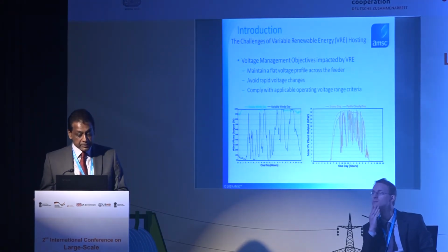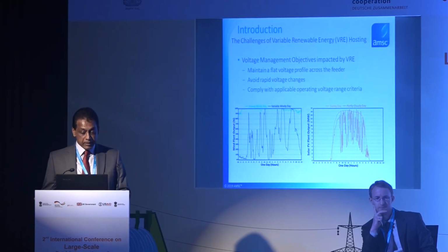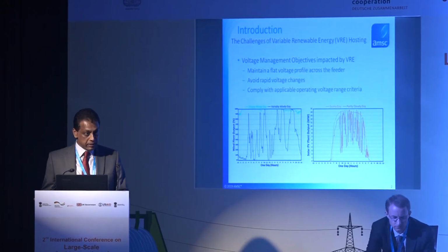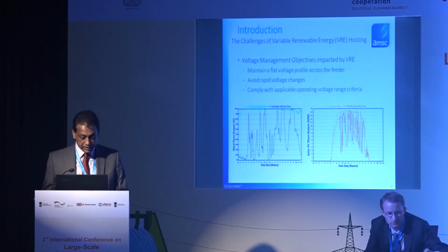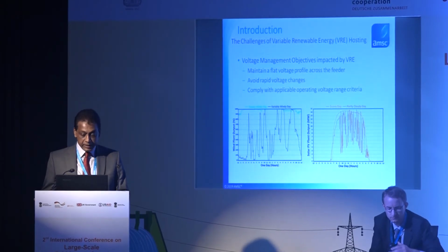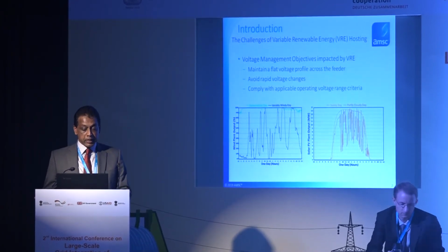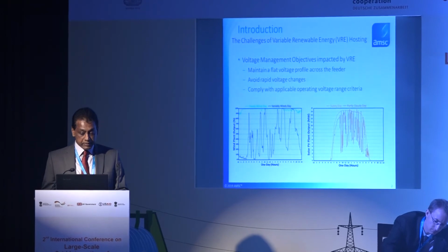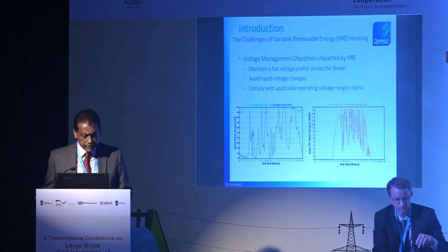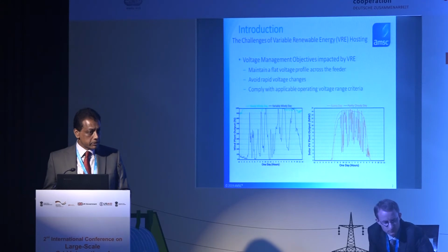On the right-hand side is a 15 megawatt PV solar plant in Arizona, US, with two graphs. The colors are not very distinctive, but one shows almost a perfect sunny day, where the output of the plant is just over 14 megawatts for almost all of the day, and then ramps down. The other is a partly cloudy day where the output of the plant drops almost 80%.